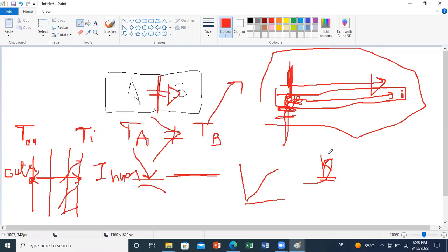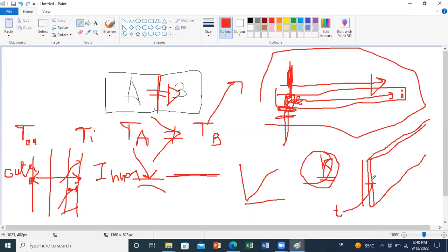This will be affected by the material you select. What are the properties of these materials? What is the conductivity? What is the thickness of the layer? We'll see in general that if you have a wall of a certain thickness, the dimensions in height and length are much larger than the thickness. This is why heat is easily conducted through this dimension, because you don't have a large distance for the flux to go over.